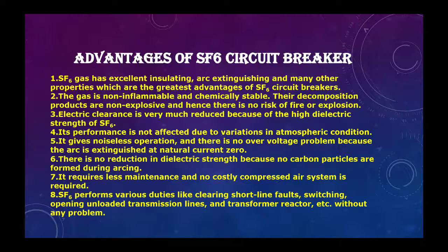Number 3, electrical clearance is very much reduced because of the high dielectric strength of SF6 gas. Number 4, its performance is not affected by variation in atmospheric conditions. So the atmosphere doesn't change the properties of SF6 gas. Number 5, it gives noiseless operation and there is no overvoltage problem because the arc is extinguished at natural current zero.